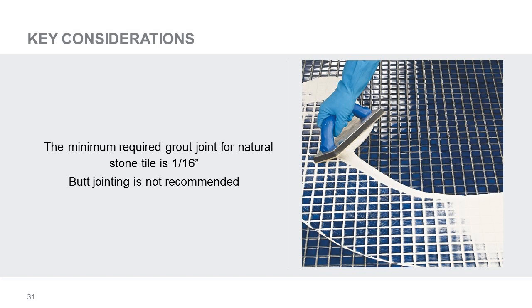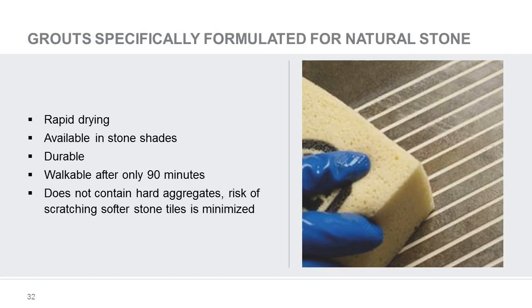Butt joining of the tiles is not recommended. Always consider movement implications and, where necessary, the mortar's ability to lose water through the tile joints to form an adequate bond. Always perform a test area also to check for scratching.